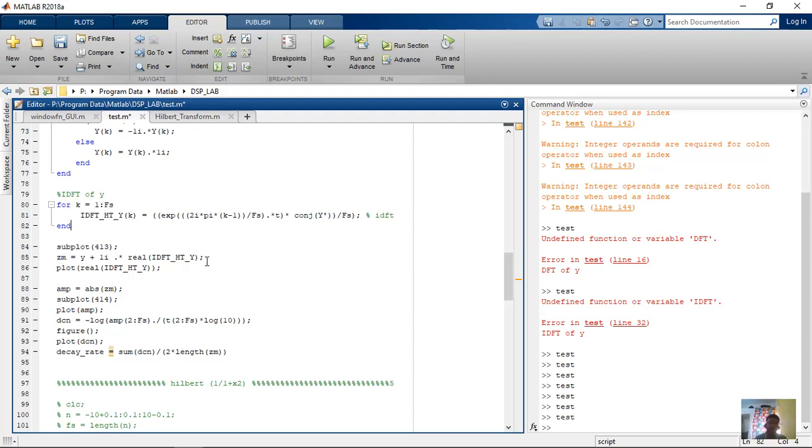So now in the analytical signal, where does the information lie? Information lies in the amplitude. So we'll be finding the amplitude of the signal. Now the amplitude response will be something like e power minus alpha n. We need to find the alpha out. So we apply ln: ln is log of something by log 10, that becomes ln of the amplitude. Once you apply the ln, you will get minus alpha into n.